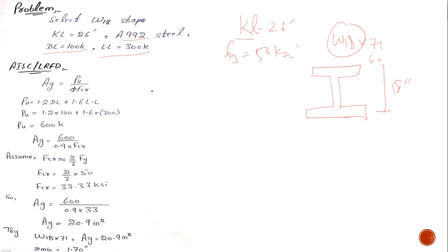Okay, first of all, I have used a very simple equation. That equation is Pu, the ultimate load, is phi Fy Ag. This equation has been used in the last lecture in the first numerical, example 1. This is the phi factor for LRFD. So here I don't know, Fy is obviously 50 ksi, but in a column a material failure may occur.